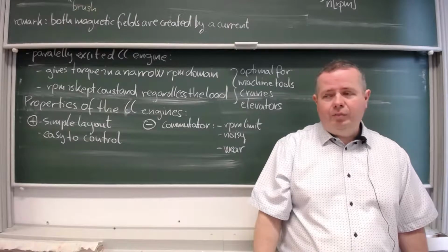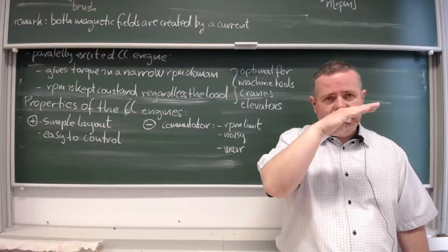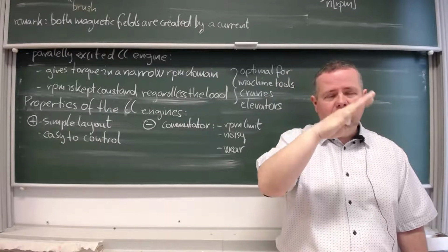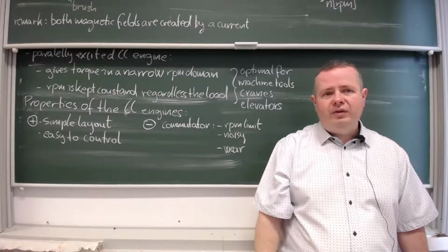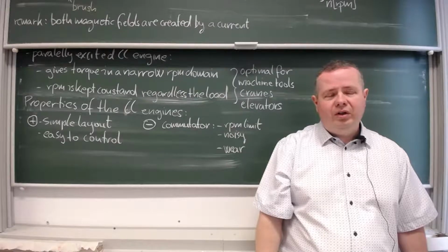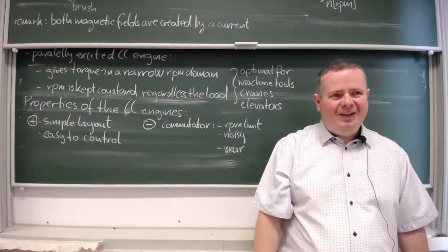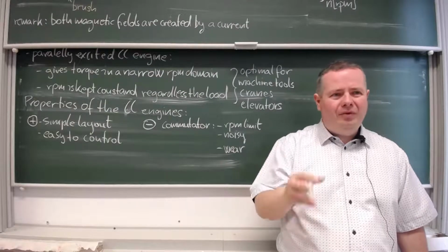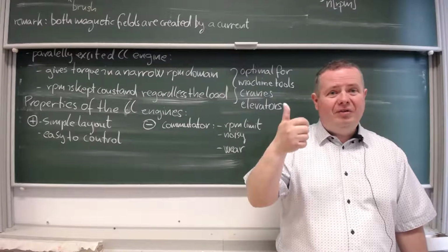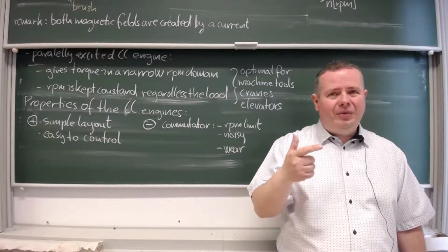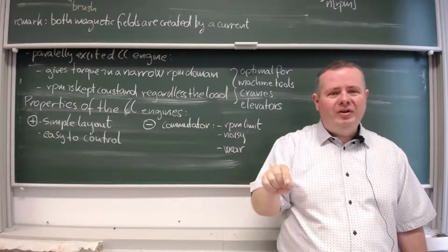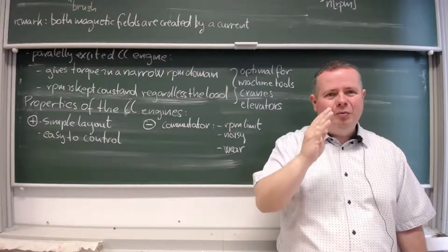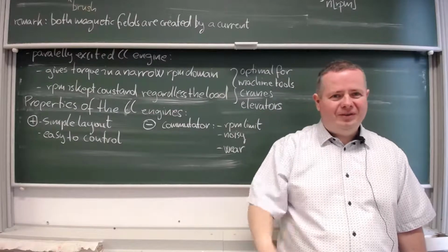And it will decrease the power of your rotor because a lot of non-perpendicular wire loops will be under current at the same time. And in the wagons, when your carbon brush weighs 5 kilograms and you get 1/2 to 1 kilogram of carbon powder on your commutator, it can make fire. It can make a fantastic annular spark system that just electrically burns away your commutator wires, commutator sheets.